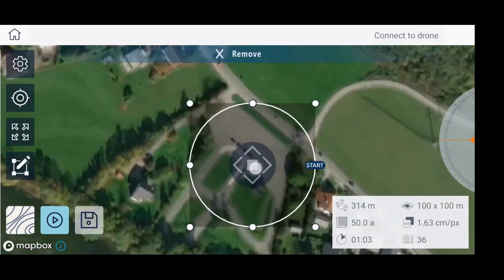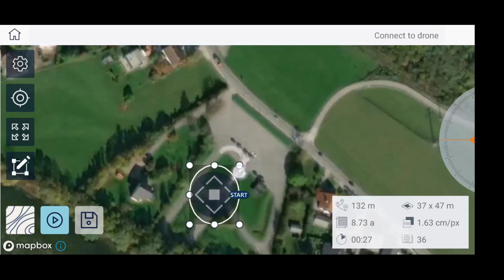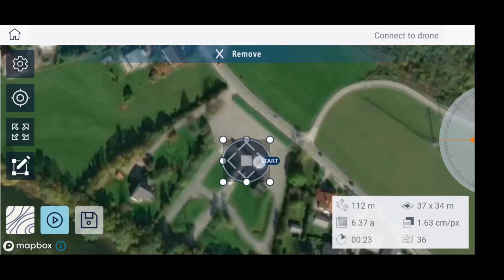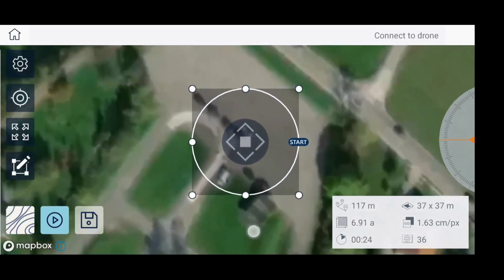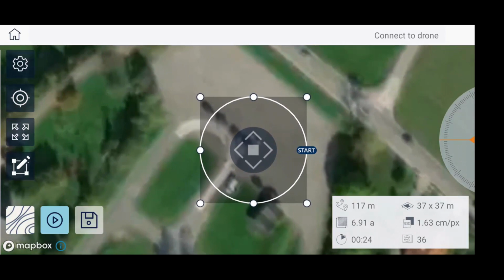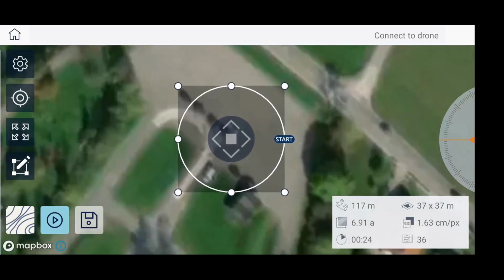Once you have the center position with the help of the drone, you can make the circle smaller and move it again over the drone icon, which will be visible there. This will take you probably a minute or two of your flight, but nevertheless you have 20-25 minutes of battery, so not a problem, and at the end you will get really accurate and nice results.